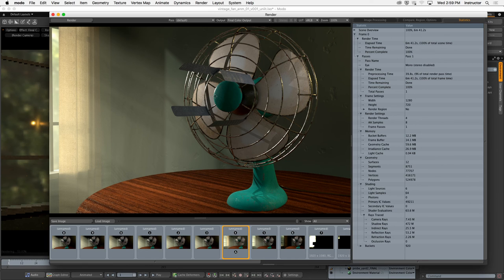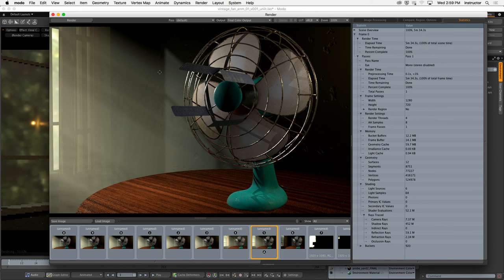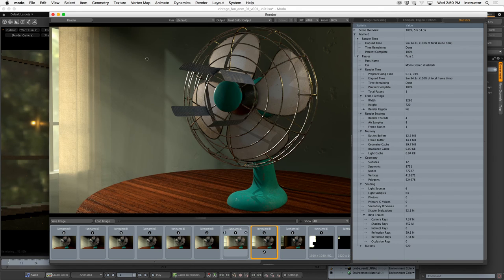What you get, the added benefit, is integrating all these shadows in here. Look at the shadows. They're pretty dark with it off, but when you turn it on in render, those shadows start to get filled in a little bit because the light rays are now bouncing around the scene itself. It's collecting illumination information on each bounce and sending that back to the renderer, and we're getting a little bit more of an accurate render.